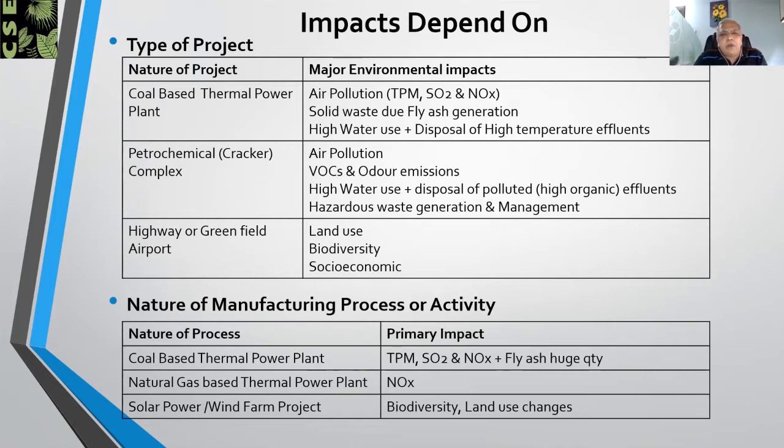Whereas in case of a petrochemical or a cracker complex, the impacts will be mostly the generation of a large quantity of non-methane hydrocarbons and VOCs, which will require proper management, and the odors which result from that, which will also require proper management. Also, the effluent in this case will have high organics, and it will be a polluted effluent. A large quantity of hazardous waste will be generated in a petrochemical or a cracker complex.